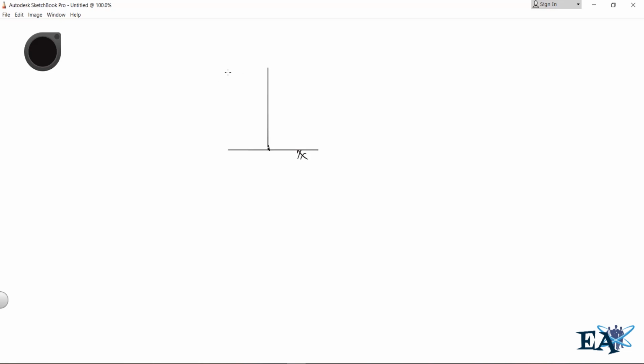So suppose that a lateral load of 5 kilonewton is acting on this structure. In that case, the structure will give a reaction at the base, that is on the ground, of 5 kilonewton in the opposite direction. So if it is acting in the x direction, it will act in the negative x direction. By doing this, the structure will be stable.